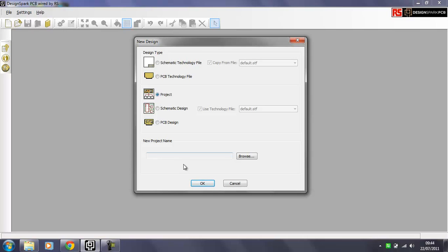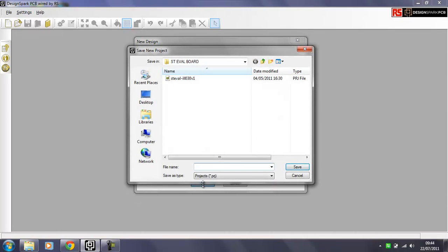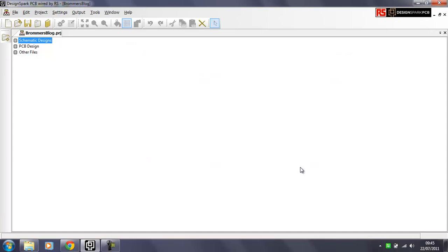So if we create the project now, and we just say OK, we basically have the option to create a new design, a project. We'll just call this one Brommer's Blog, and we'll save that here. Instantly, we now have a tab open called the Brommer's Blog.prj, the project file. Here you've now got three options: schematic designs, PCB design and other files. Here we're now able to add files to this design.